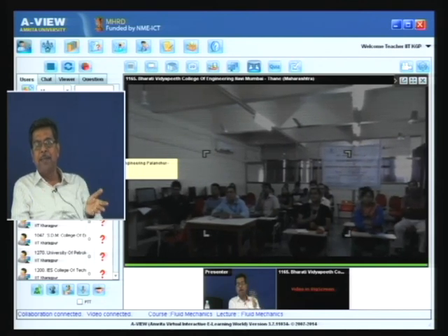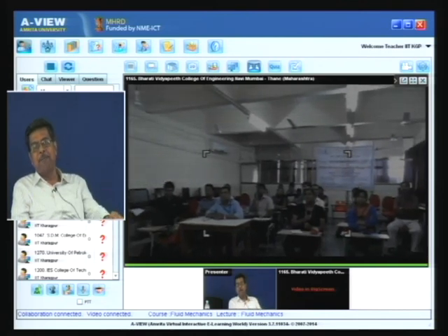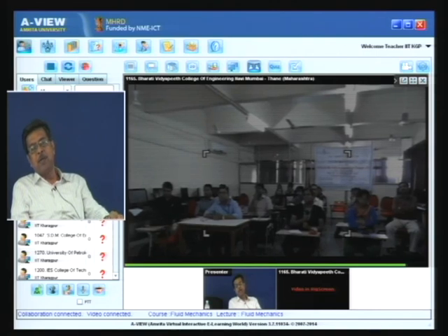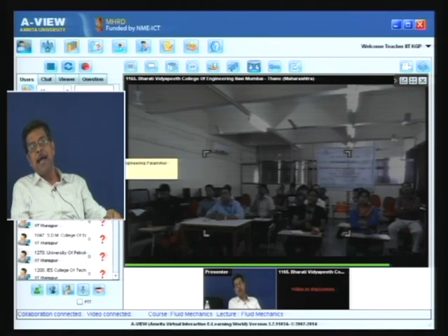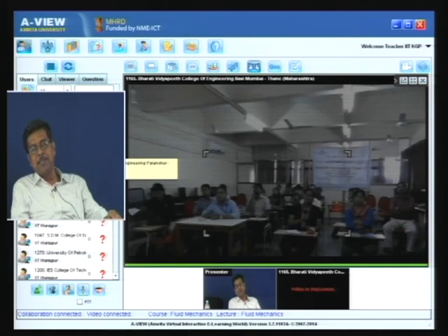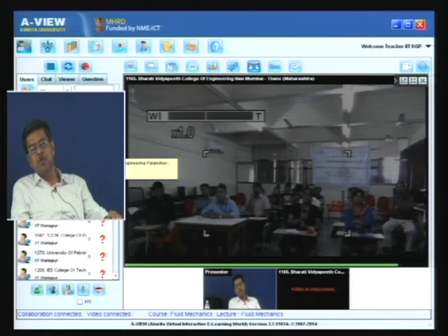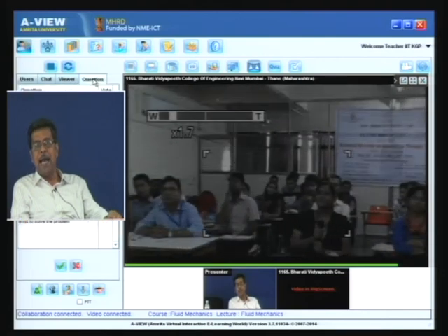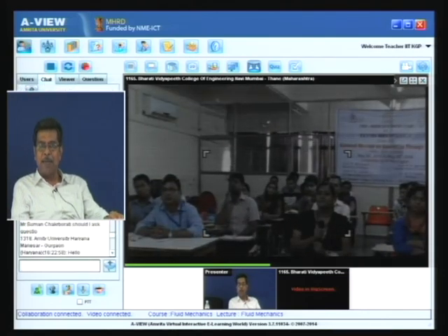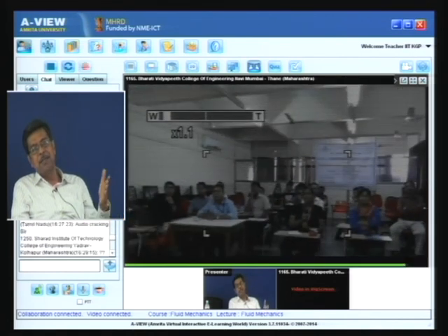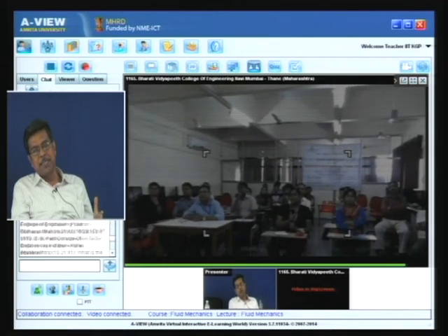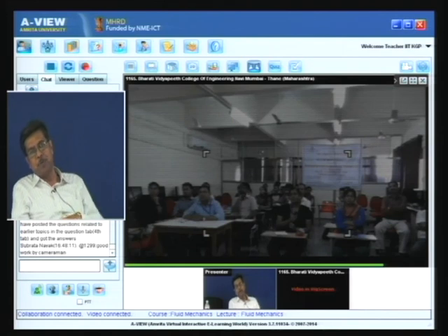For example, when you write the continuity equation in an integrated approach over a cross section, we write that rho 1 A1 V1 is rho 2 A2 V2. Inflow and outflow areas are A1 A2 and V1 V2 are the average velocities over the cross section. This is one example. The integrated approach is used when we are interested in the average behavior over a surface or over a domain. And RTT is a particular example that relates the law of physics of a system to that of a control volume, and that is done through the integral approach only.